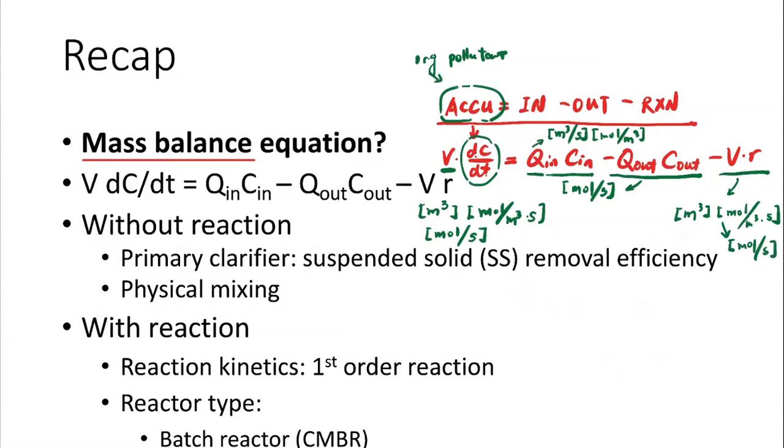So that's why we always need to pay attention that whenever we list out this mathematical equation, we need to include the volume term for the accumulation term and the reaction term. One thing that I also point out is that there's a restriction regarding the reaction term, where R has the unit of mole per meters cubed per second.